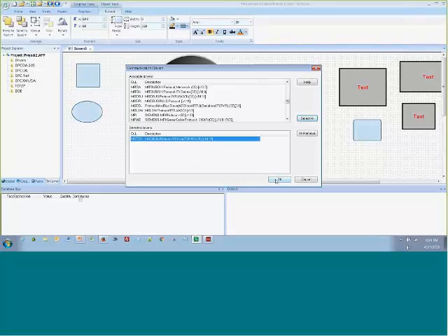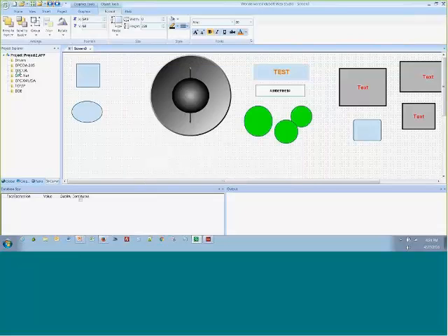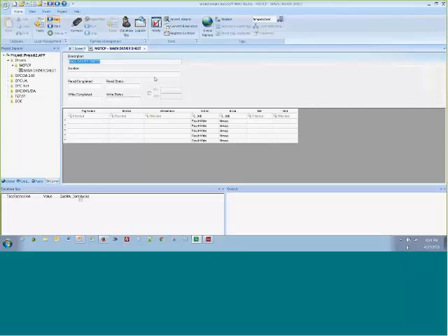So for example, I've got this Modbus driver loaded, and now when I do that, it gives us this main driver sheet. And if you know the difference between the main driver sheet and the standard driver sheets, in the main driver sheet you can put in any PLC, multiple different PLCs, and any PLC I/O address. So for example, I could have a PLC in here, let me just give you an example, 192.168.1.200, and I know Modbus PLCs need the port number and then the PLC ID number.